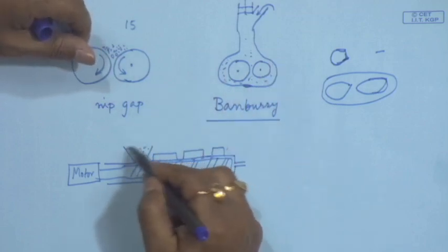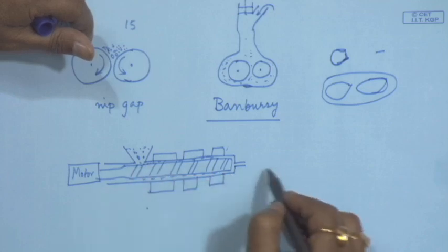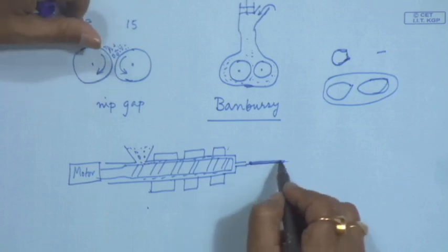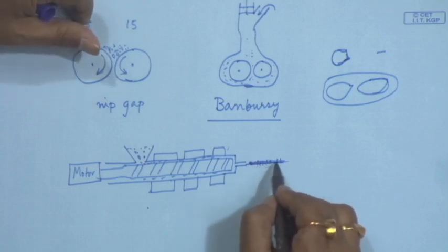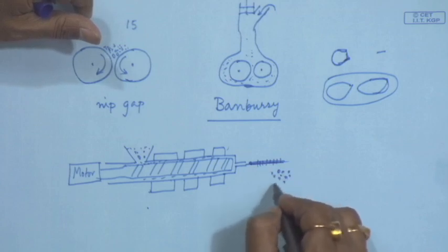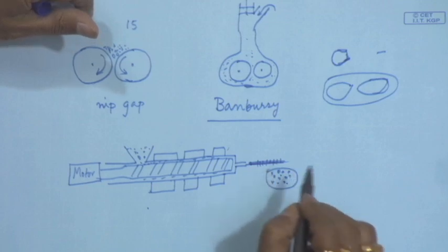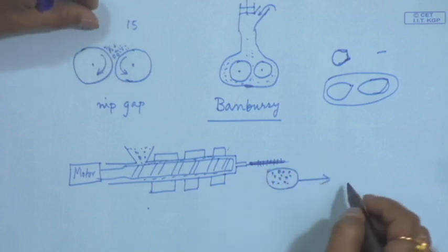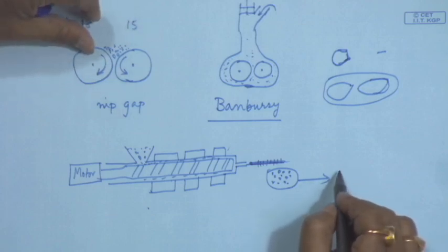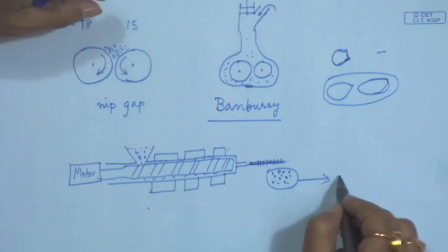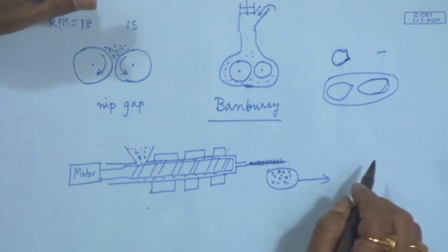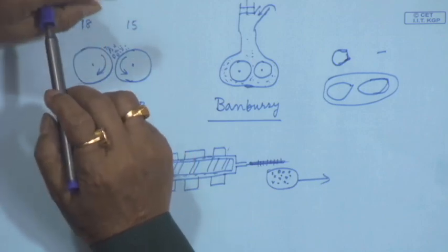Continuously polymer is fed to the extruder through the hopper and continuously this polymer, after mixing, comes out and it can be chopped to form mixed polymer granules. So, in the form of granules or tablets or rods we can have the blended polymer. Then this can be further used for subsequent processes to make different types of products. Say it can be used for injection molding of products, or for extrusion of pipes or tubes or insulation and covering of electrical conductors.